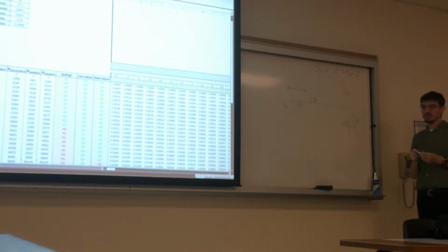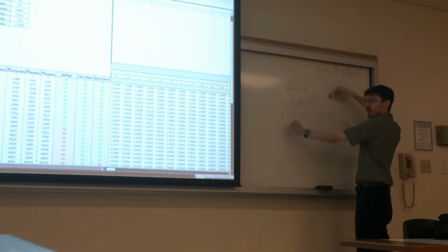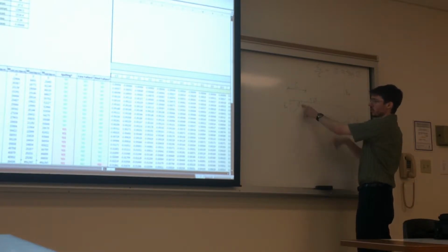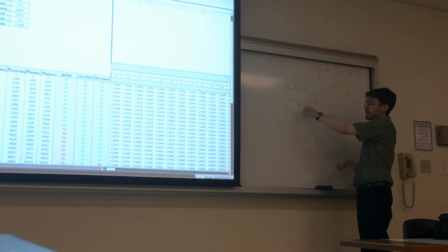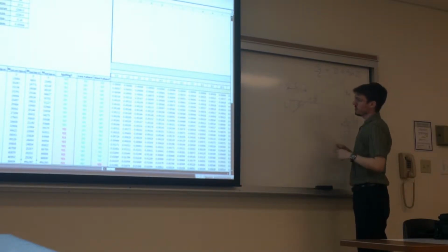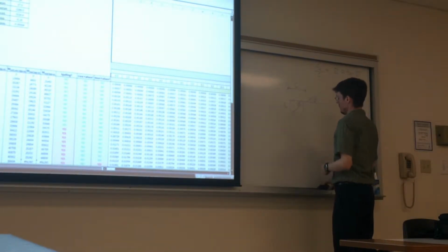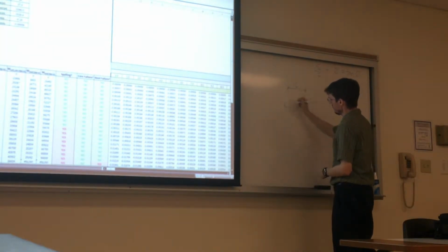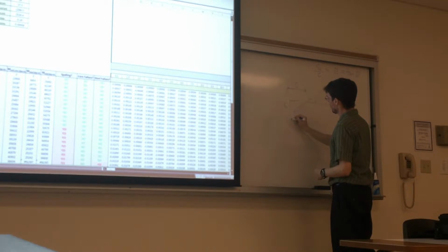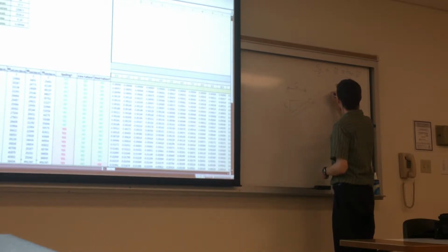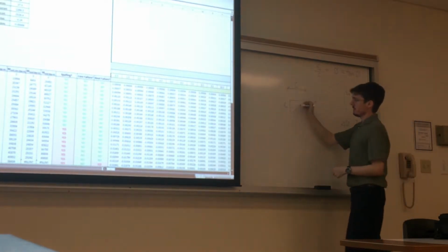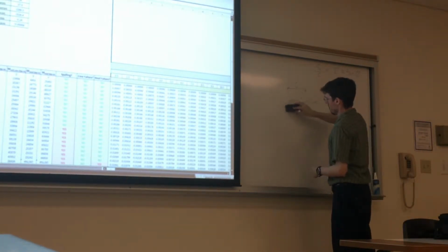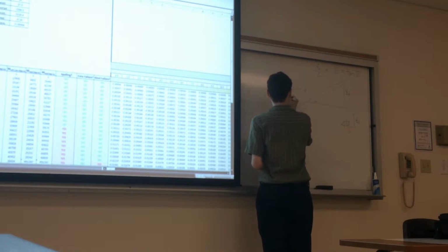And so then what you're doing essentially is you're moving this profile up and down, right? This curvature is a constant for your given increment. Your curvature doesn't change. So by changing the depth of your compression region, you may go down, for clarity's sake, and have your next guess be like this.